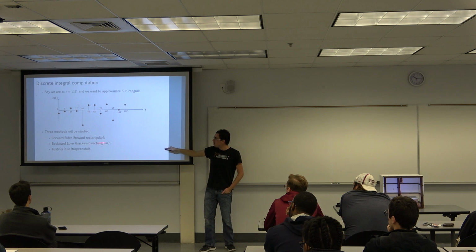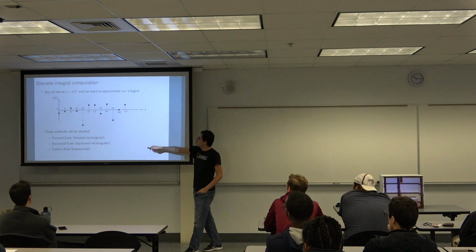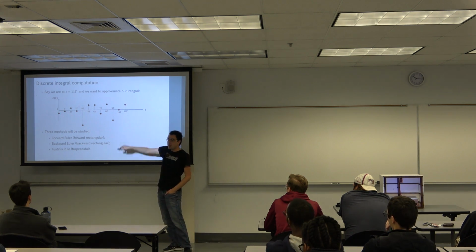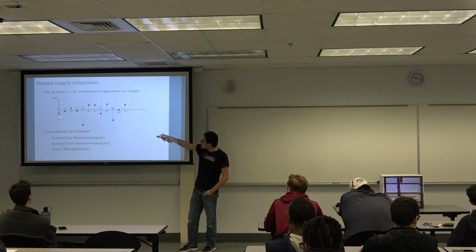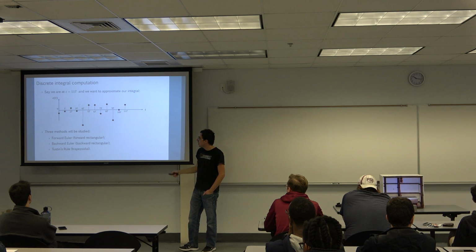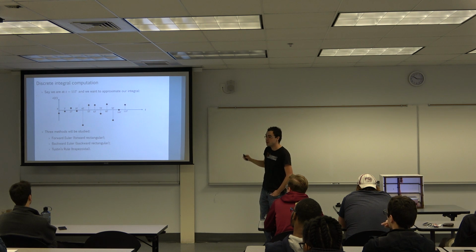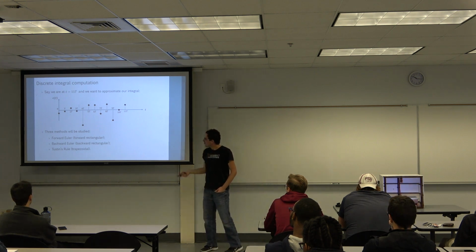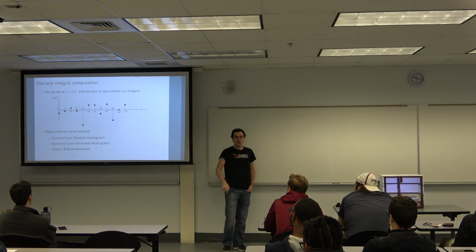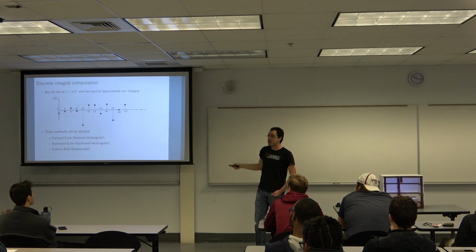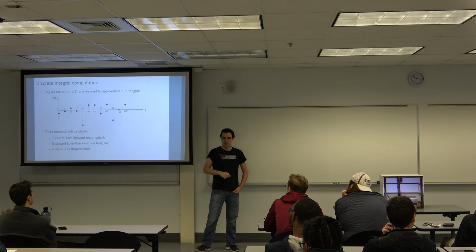Those are called the forward Euler, which means we're going to use forward rectangular windows, so we drop the last sample and then we integrate forward. We can drop the last sample and then integrate backwards. Or we can use Tustin's rule. It's called Tustin's rule, not Justin's rule. And this is just trapezoidal integration, where you average the two points to come up with a single point, and then if you have 12 points and you take averages between them, you get 11 points. That would be enough for the integration.